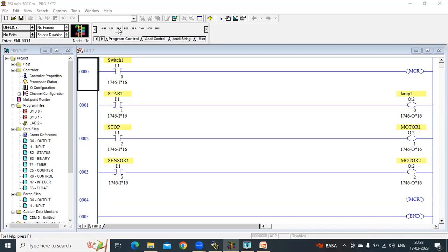So we are dividing these logics into small blocks and calling them according to our execution order. In whichever order you want to execute, that way you can call these blocks. For that we are creating sub-blocks, also known as subroutines. Subroutine blocks.